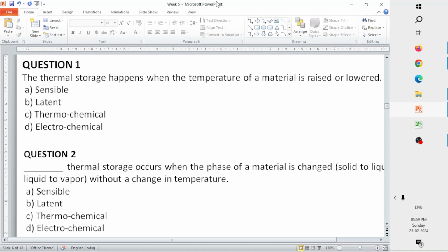That is not relevant to thermal energy storage. Over there the main mechanism is Faradaic and non-Faradaic, that is redox and non-redox reactions happening in the system, which help in storing the charge and the energy. So that is not correct. Thermochemical: we discussed that in thermochemical storage you drive an endothermic reaction by reacting two components. Your solar energy is absorbed in that process, and then you form the products. These products are going to be stored.